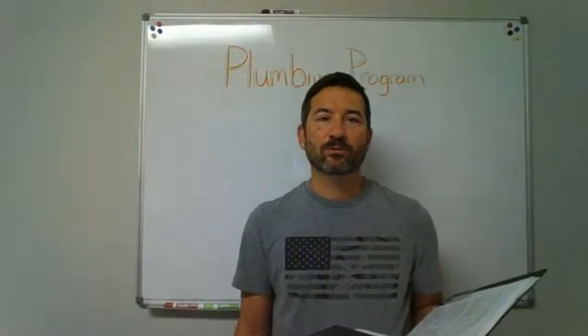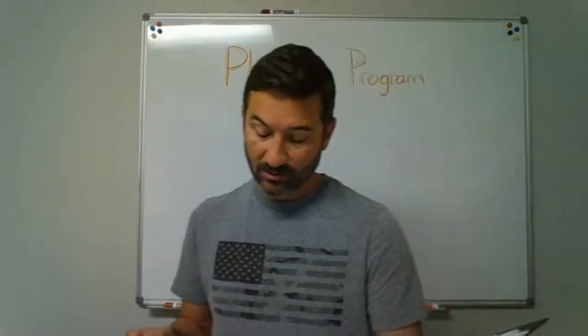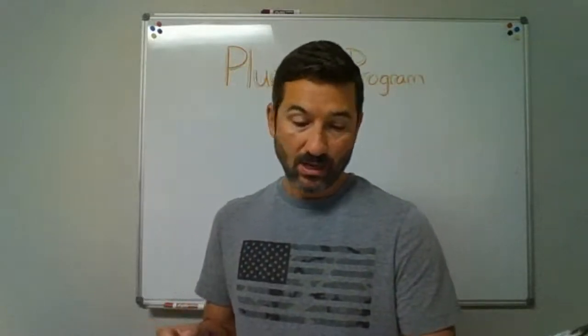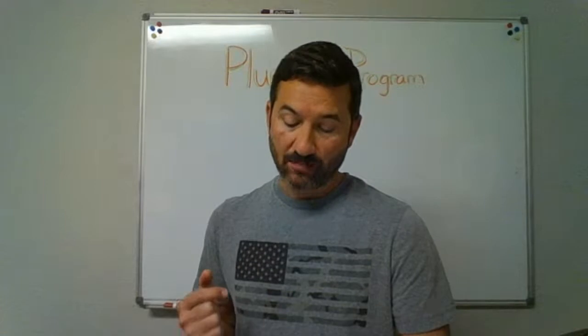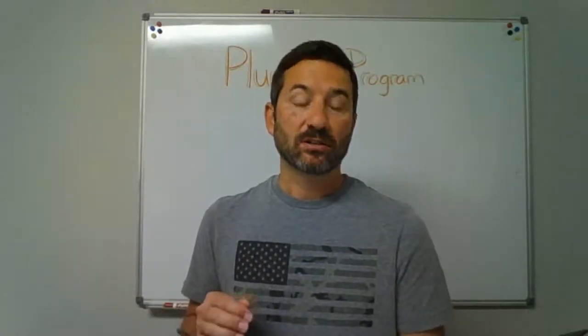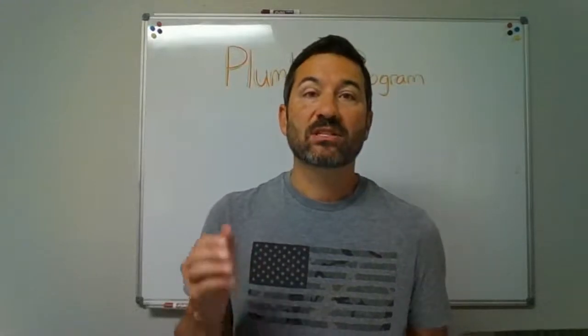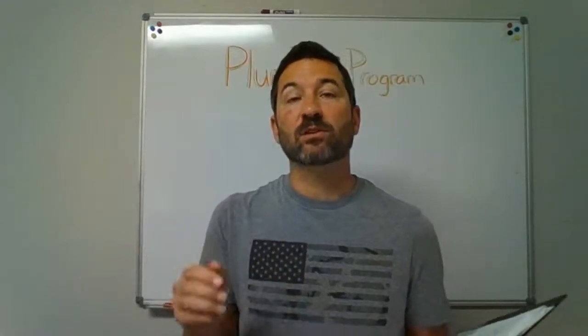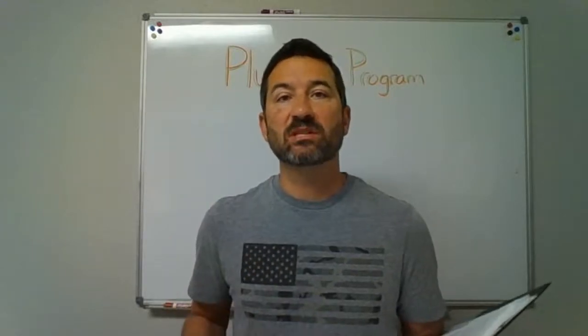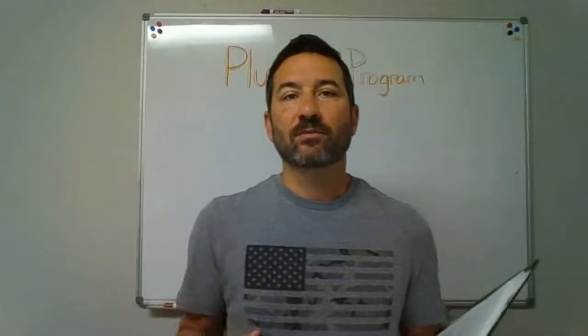All right, we're back with chapter 9, part 2, on the venting chapter. In chapter 9, we're going to pick up today at page 79. Where we left off was on page 78, and we talked about looking at section 909. We talked about the distance between the trap and the vents. We looked at the minimum distance, maximum distance, all that information between the trap and the vent.